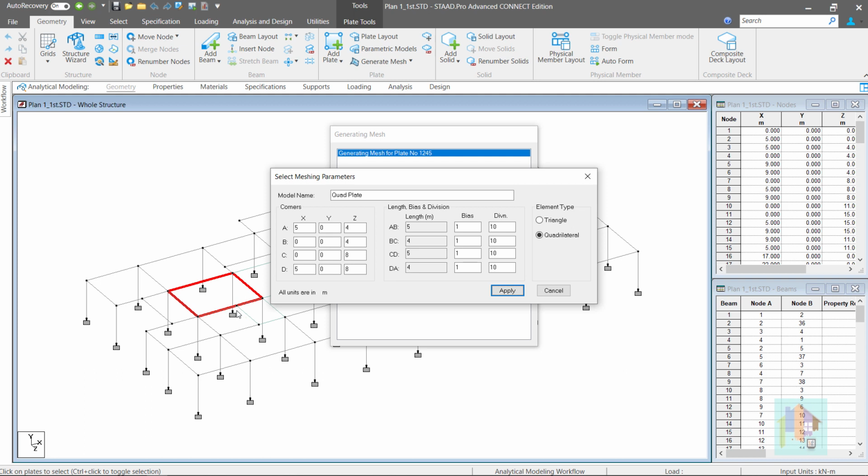This plate edge is 5 meter long with a junction at 3 meter distance. Edge division 10 or 0.5 meter plate segments will add a plate at this junction. So it is okay. But if the junction is say at 3.3 meter distance, then either we have to create more plate segments or manually adjust the plate connectivity as discussed in part 1.